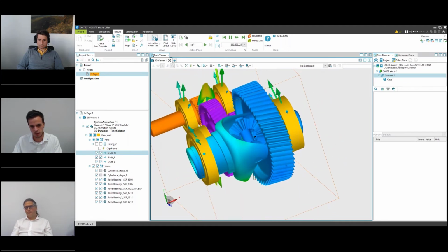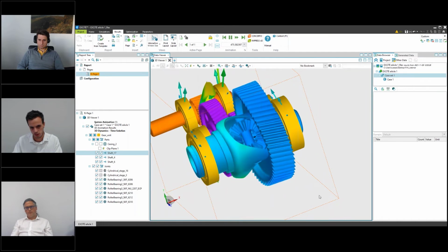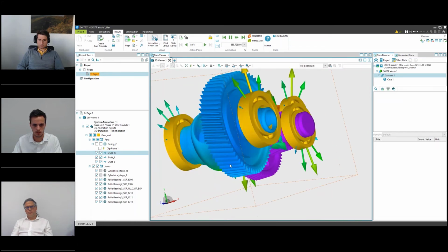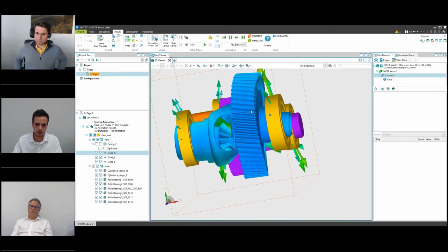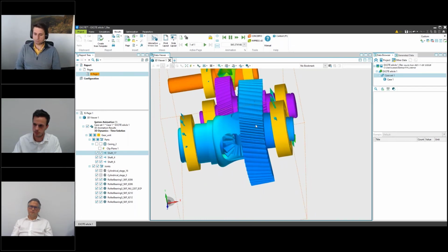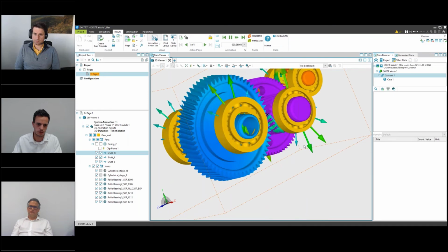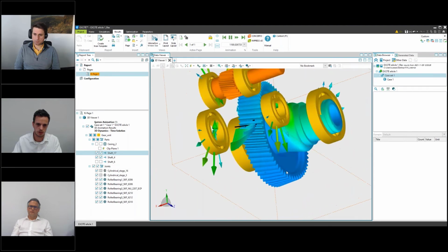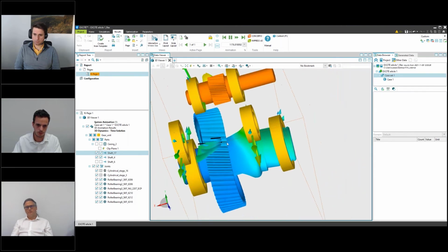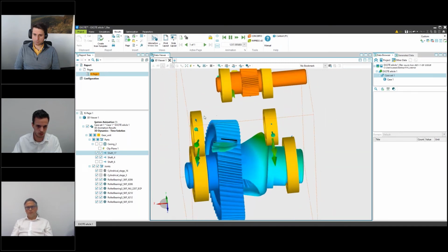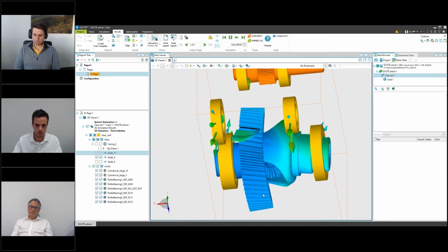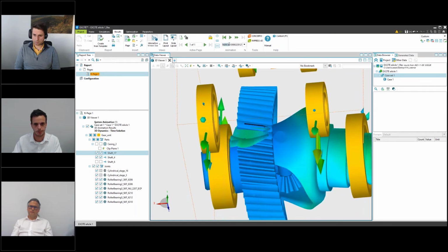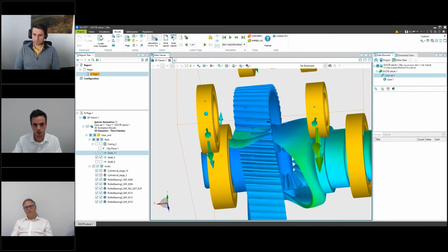So probably the design of the differential is not rigid enough. It seems to be too weak, and it's also tilting. You can also see the gear. The shape of the gear is significantly changing. And this, on the other side, if you now have a look at the force distribution, is exactly causing this force distribution. Sorry. Rotate the gear so that you can see properly. The shape is really wild, I would say, and this is causing this edge loading case of the gear.